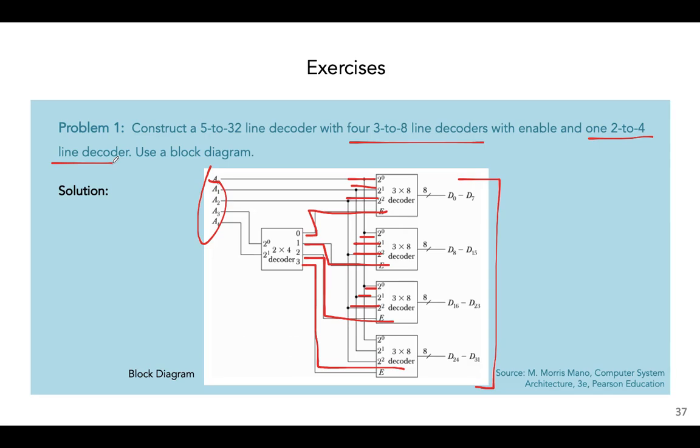So all you have to understand here is we just need to design a circuit which has the necessary number of inputs and outputs, and then we have to find a way to combine multiple inputs into a single input line if necessary, right? So if you have more input lines than what you currently need, you have to combine them. You have to use taps, or you can use the same line converted into 2 different lines using an inverter, like we did when we were discussing decoder expansion. So the idea is to either combine multiple input lines into a single line if you need to reduce the number of incoming input lines, or if the reverse case arises, you have to find ways to increase the number of input lines.